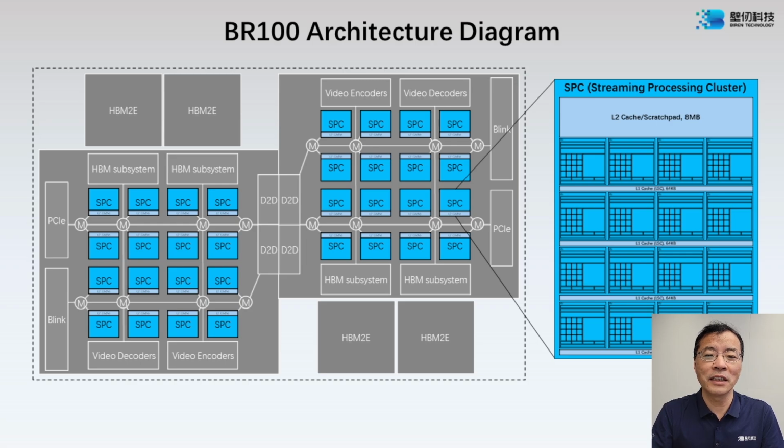Hi, this is Mike Holm, CTO of Biren Technology. It's my pleasure to introduce architecture details of the BR100 GPGPU. BR100 is designed for data center AI training and inference. We have 2 design goals for BR100. The first, it needs to reach 1 petaflop horsepower. The second, it should be a GPGPU, not a pure AI accelerator, which means we will provide our C compiler, which will be able to compile kernels written in an OpenCL-like language for better programmability and easier compatibility with the ecosystem. Let's have a big picture first.